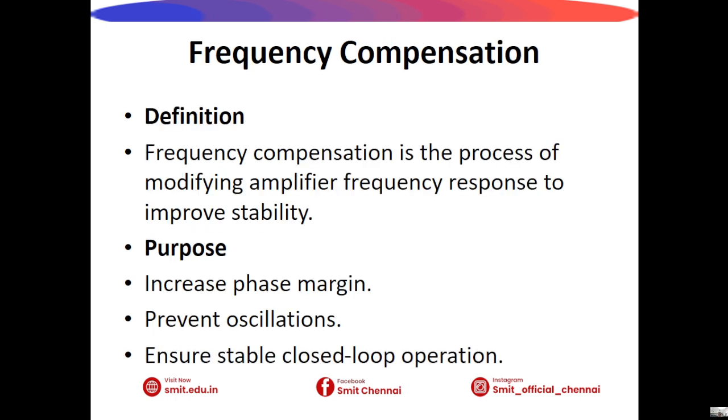Next, we see frequency compensation. Frequency compensation is a technique used to improve stability by modifying the frequency response of an amplifier. The objective is to reduce excessive phase lag and increase phase margin. Compensation ensures that feedback amplifiers operate reliably without unwanted oscillations.